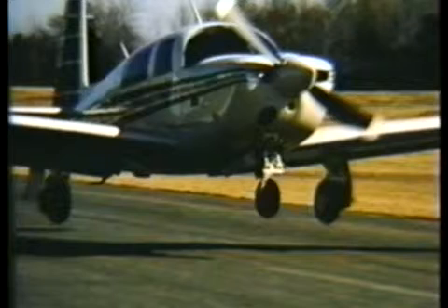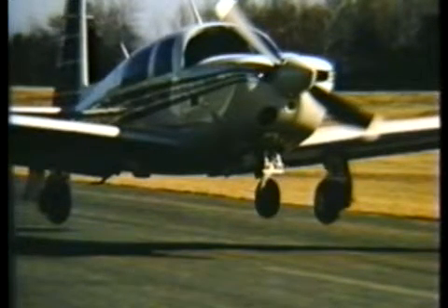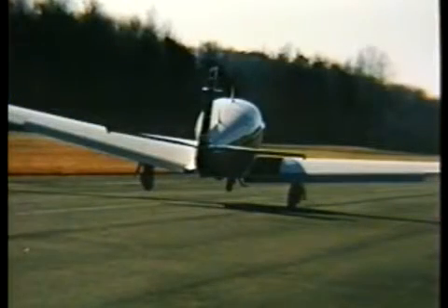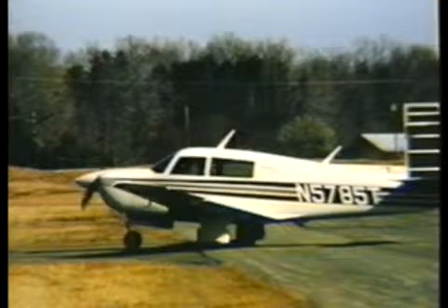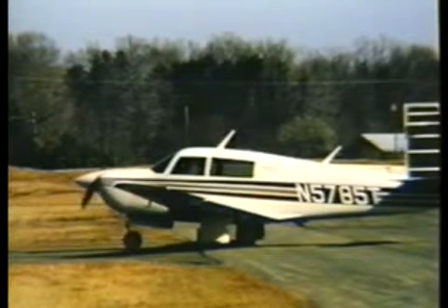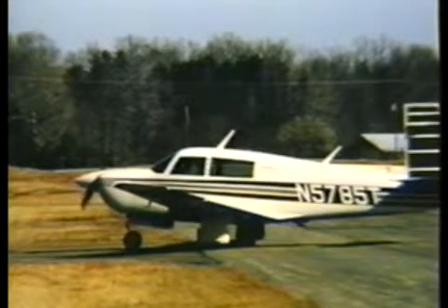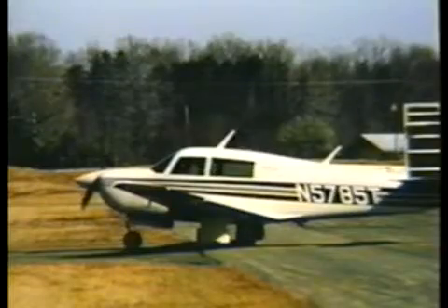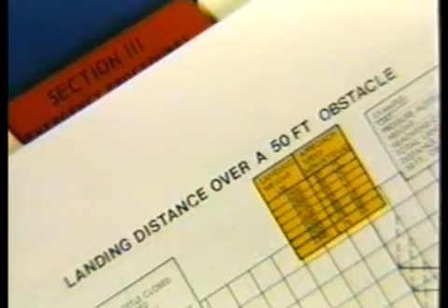You see, your airplane's stall speed was lower because the plane was lighter. And your airplane floated in ground effect because it was still approaching its actual landing speed and just wasn't ready to land. The point we're making here is that 600 pounds can be just as significant a difference to a small plane as 100 tons can be to a heavy jet. And there you have another important lesson about landing, that you must learn and fly the appropriate approach speeds for different landing weights.